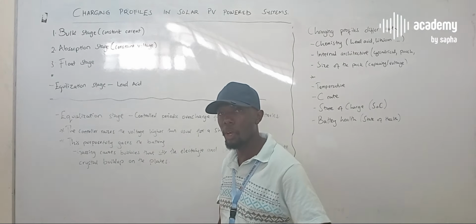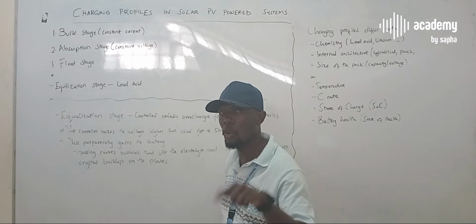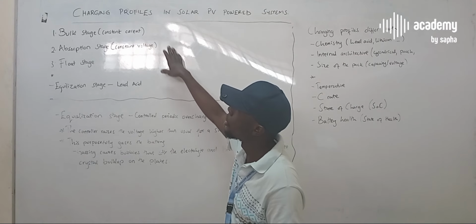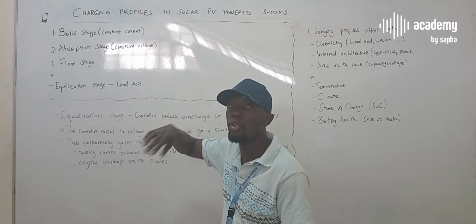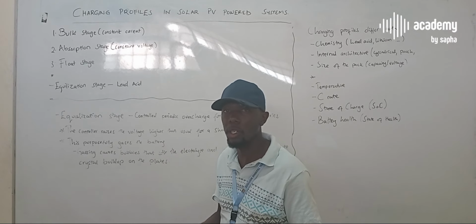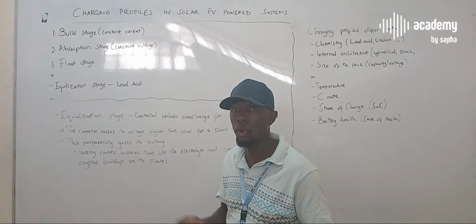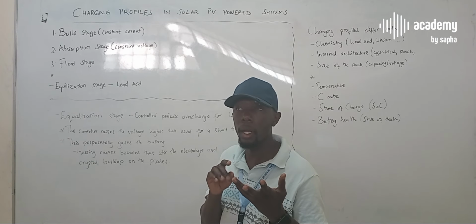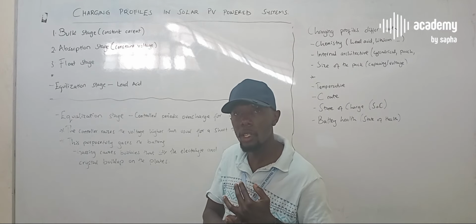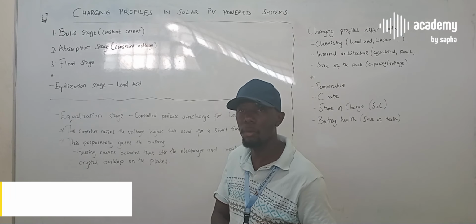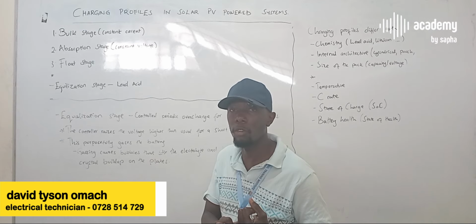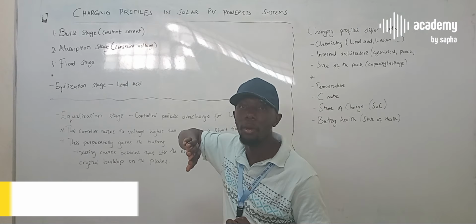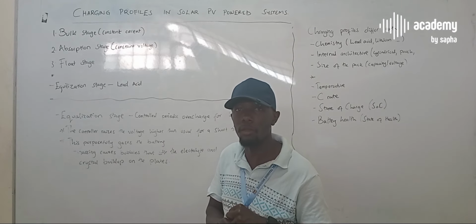If you link it to a lithium ion battery and you inform it by keying in all that information, they have options for that. The charge controller will now change the charging stages to conform with what a lithium ion battery needs. And so in our next session, we shall look at how the different voltages vary for different batteries, and apart from the voltages, the effects of not following the charging stages in your battery bank or in your solar PV system.